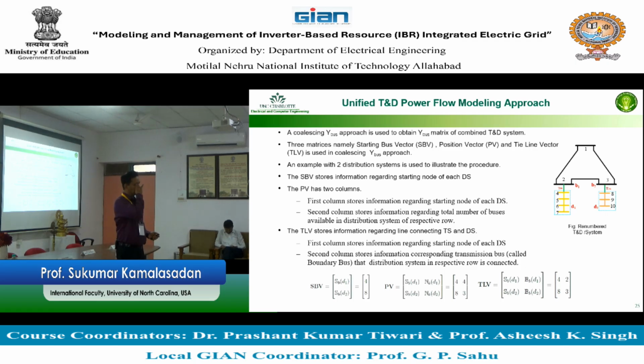All the time, the transmission system output, which we call the head end, or the node where the distribution system is connected, that voltage is the first point that you maintain. And you maintain that voltage based on the entire electric grid load, including the distribution grid load and the transmission system stability. Most of the time you maintain that voltage within the limit of 1.05. You cannot maintain 1.1 basically. That's the max which you can do. That is the source side of the OLTC, the LTC transformer, the source side of the transformer. So you maintain that voltage.